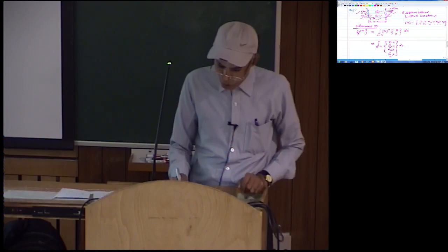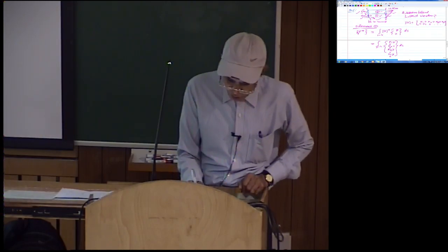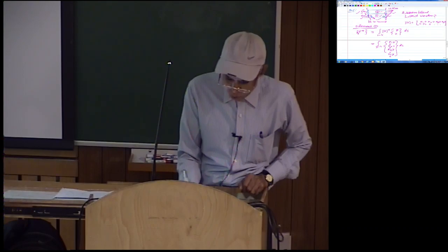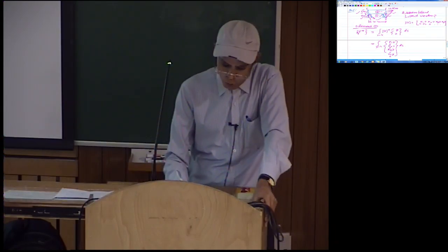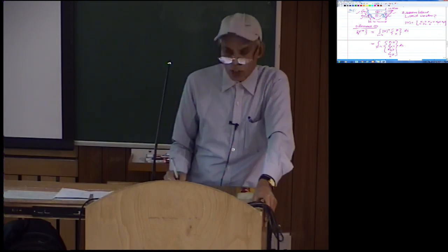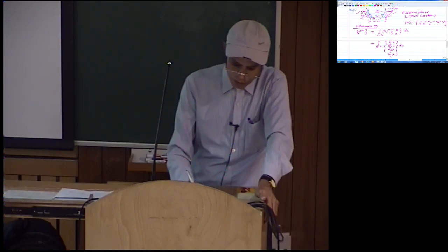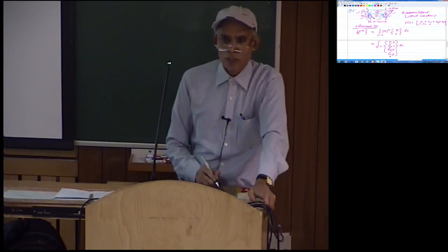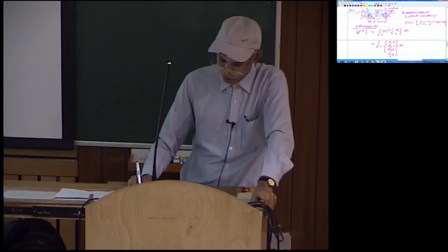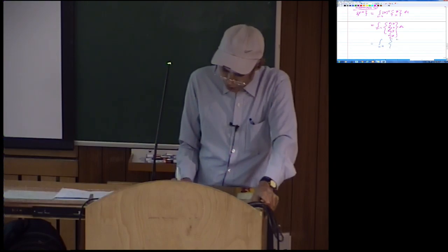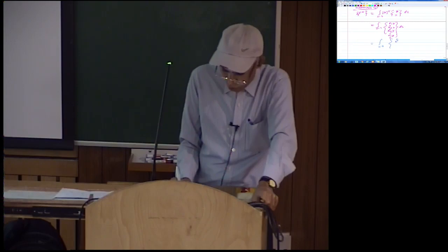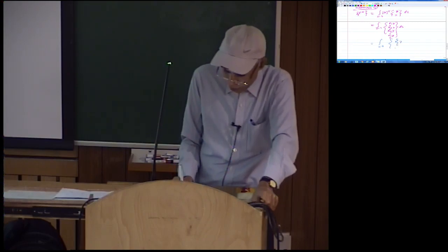So now these are local node numbers. You will also have local node number, say local node number here 1, this is local node number 2, this is local node number 3, this is local node number 4 for the first element. So along edge 2 to 4, that is local node 2 to 3, you only have non-zero values of N2 and N3. N1 and N4 are the shape functions corresponding to this node and this node, so they will be 0. Now you can of course cross check from the expressions for the shape function. So then finally what you need to evaluate is 2 to 4, and these two become 0, then you have N2 non-zero, so N2 into Y 0, N3 is non-zero, so N3 into Y 0, and then 0 0.